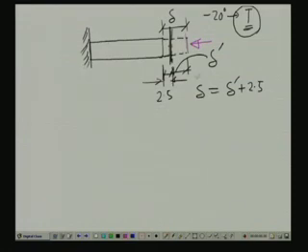That means this additional deformation delta dashed, which is getting caused from the wall to this end, has to be brought back to this particular position, and for that I will have to apply a load P, and this load is going to cause a stress in the bar, which is equals to P divided by the cross sectional area.